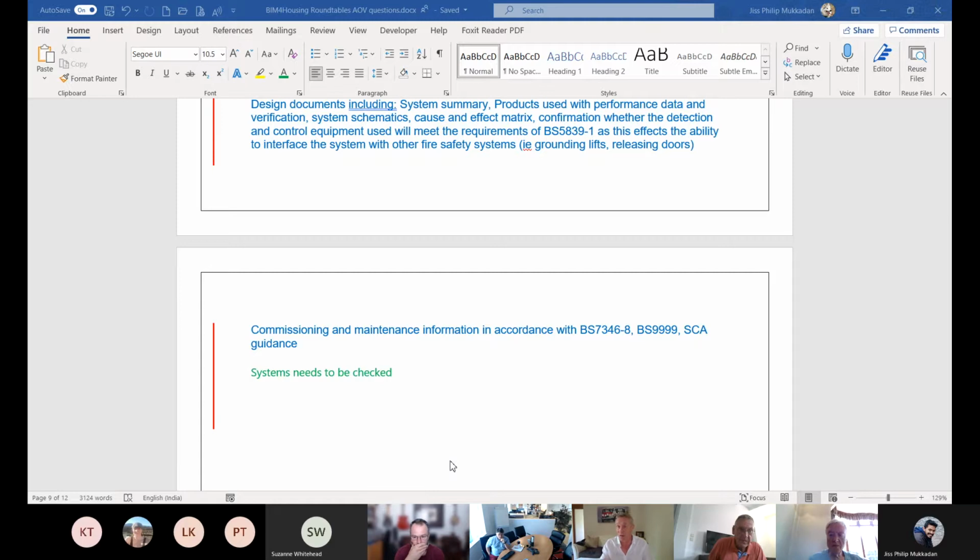It's common in all fire alarm technologies. But part of accessing that software is you have to be competent to know what you're doing, because there's got to be an audit trail of the changes that are being made, because if you're not knowing what you're doing, you reconfigure a fire alarm system and it makes it more dangerous.